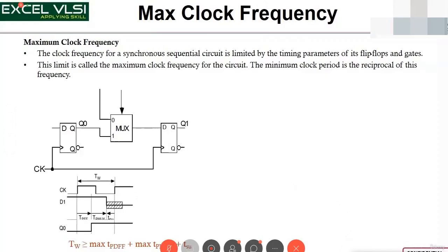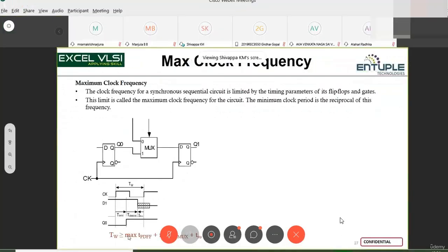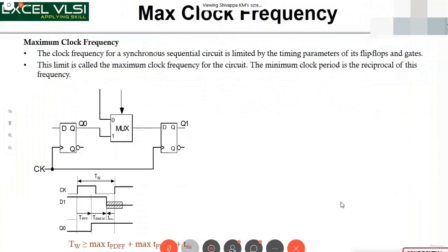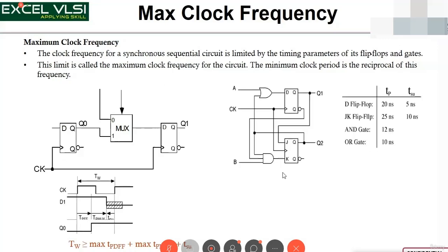There will be some clock skew and a lot of clock uncertainty. There are other things which will come, but those are comparatively small numbers. The important delays which will be considered for the timing analysis are the clock to Q delay, the combinatorial delay and the setup required. Further, Shravanti will explain launch path and capture path in STA terminologies, but understand this basic concept.